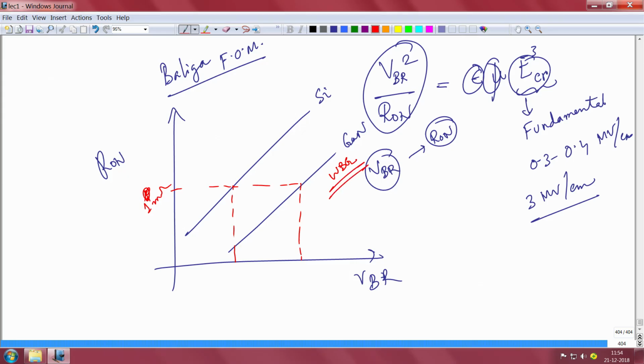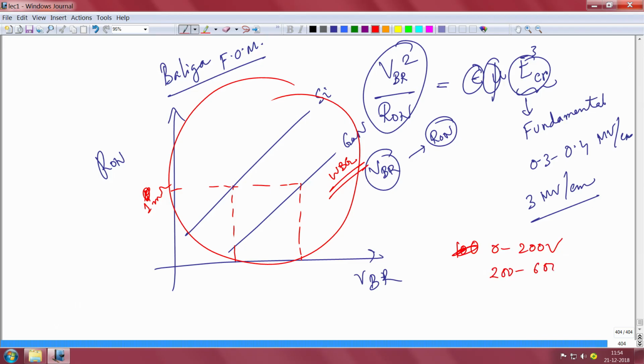It doesn't mean that they are going to replace silicon just like that, because silicon has a very large market, and these power switches have their own markets. Are you talking about low voltage, like 0 to 200 volt sort of applications, LiDAR applications, or some other low power things, or are you talking about 200 to 600 volt applications that might include solar inverters and many of the charger DC-DC converters, motor drives? You might also talk about 600 to 1200 volt applications, hybrid vehicles, and a host of other applications. You might also talk about locomotives, where you have 3 kilovolt, 2 kilovolt applications and so on. So there's a market size, there's also a cost component to it.